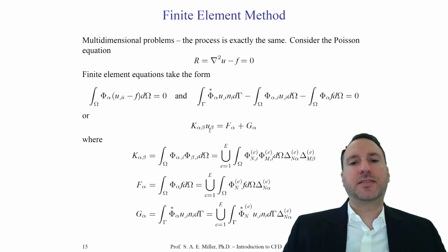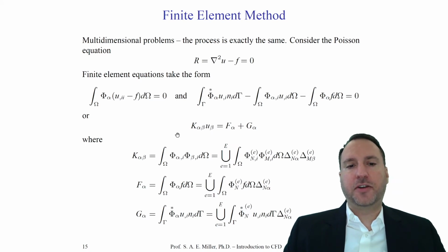We can solve this with the same linear algebra solvers that are developed in linear algebra classes. And we'll talk about those later in this section, the linear algebra solvers. So these can be applied, of course, for linear equations. The Poisson equation, Laplace equation, etc. are all linear equations. So we have to make sure that we use a linear solver for them. If we have a nonlinear set of equations, for example, then of course the formulation becomes much more complicated. But this is the basis of the finite element method.